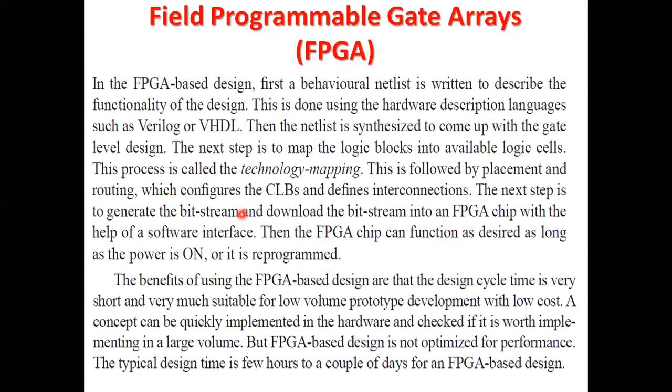Now in the FPGA based design, first a behavioral netlist is written to describe the functionality of the design. This is done using hardware description languages such as Verilog and VHDL. We will be studying all this in the VLSI practical classes.